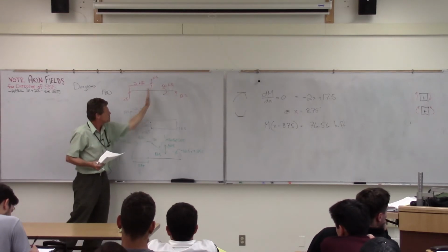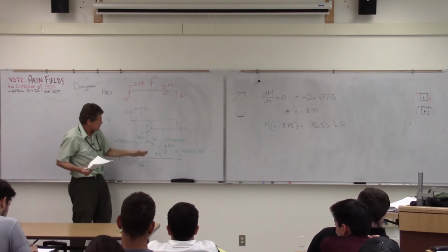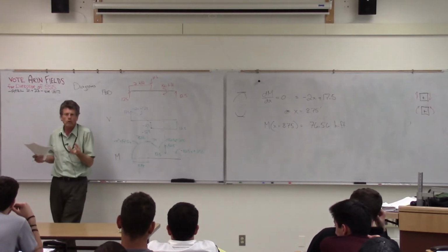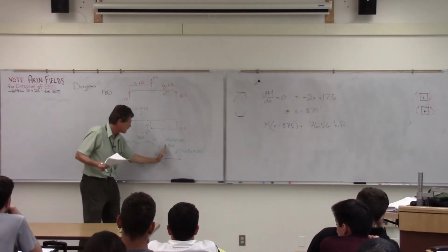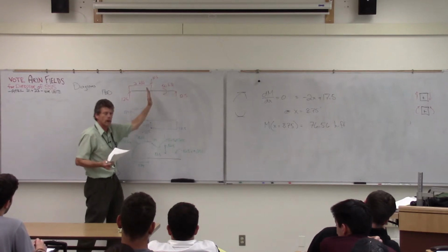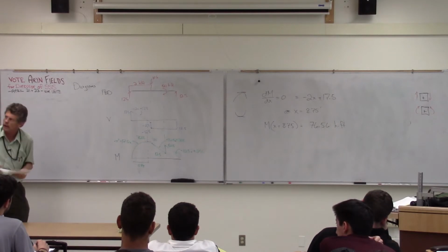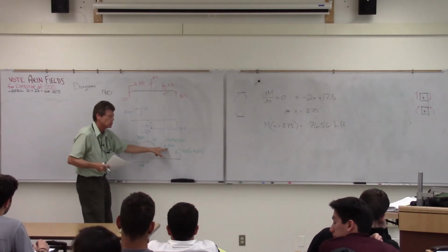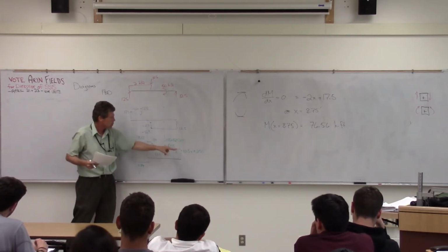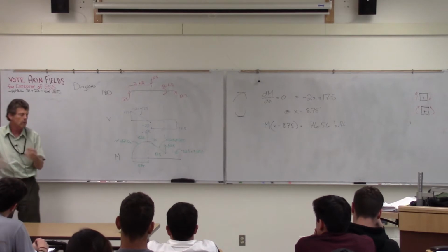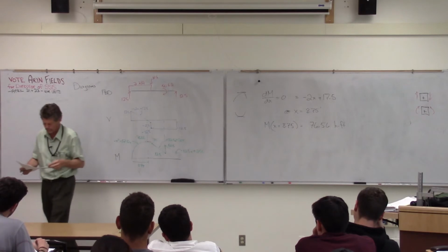Then as I make a cut through this area here, nothing's going on in terms of load. No load's being added in that section there. So basically, my moment diagram's only a function of x, only a function of its moment arms. Move along there linearly, it's starting to come down, and then I make a jump. I cross that point C. There's a concentrated twist. My equilibrium equation says, OK, I've got to pick up that concentrated twist. The way I do it is in my diagram, like so. Do that little jump. And then with the equation, plug in the values. It goes back to 0, again, at a pin or a roller connection there, because there's nothing restraining the rotation there.